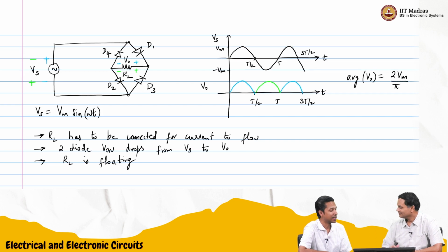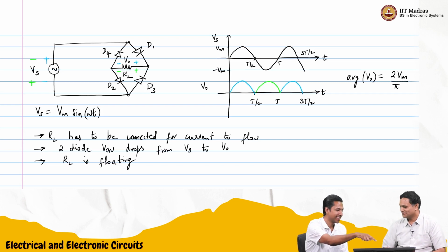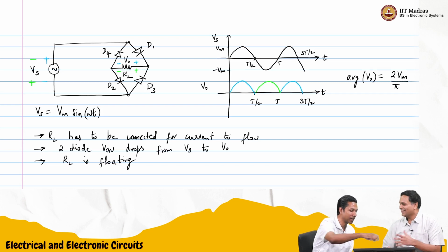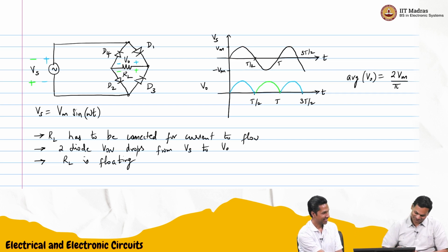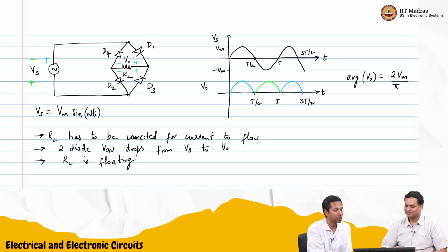Because when we were doing experiments, if you use an oscilloscope, I mean, it has two terminals, one always connected to ground. If you connect the probe across this, one terminal will be grounded and then it will be a problem. Correct. But with the kit that we are using, I think there is no problem.